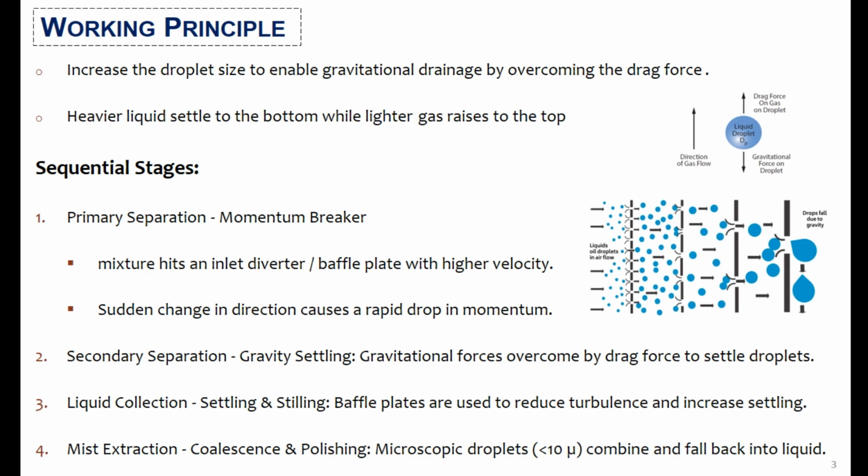The working principle of a separator is based on overcoming the drag force. In a separator, droplet size is increased to enable gravitational drainage by overcoming the drag force. In this way, the heavier liquid settles to the bottom while the lighter gas rises to the top.